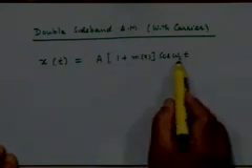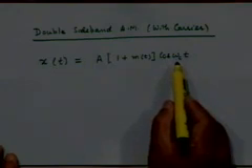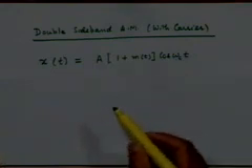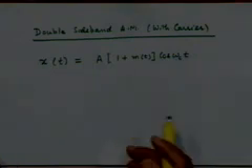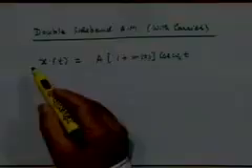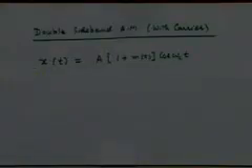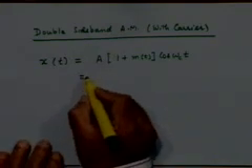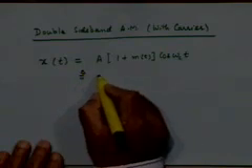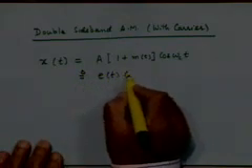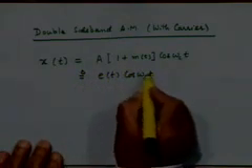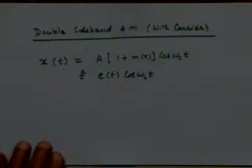But we are also adding a term which is equal to A cosine omega c t, right? Which is a carrier term. So there is a carrier component specifically introduced along with the message signal, along with the rest of the modulated signal to produce the final modulated signal x of t, right? And let's define this as some E of t into cosine omega c t, where E of t is defined as A times 1 plus m of t.